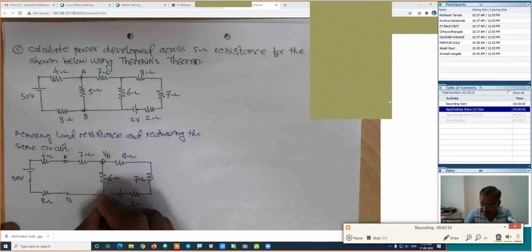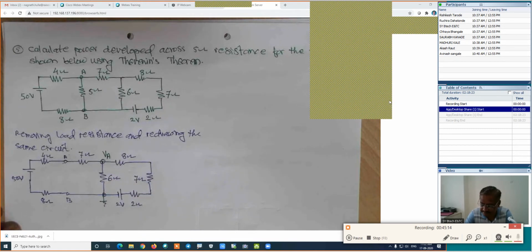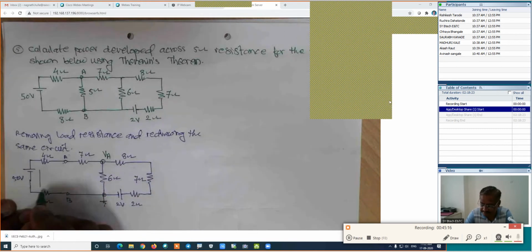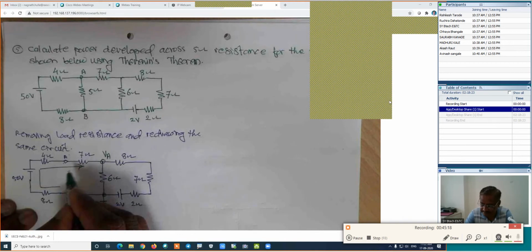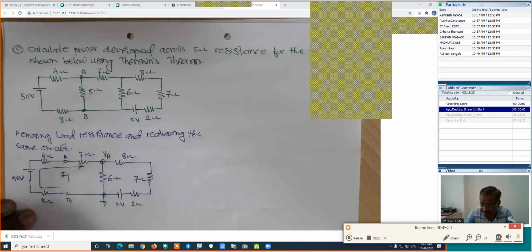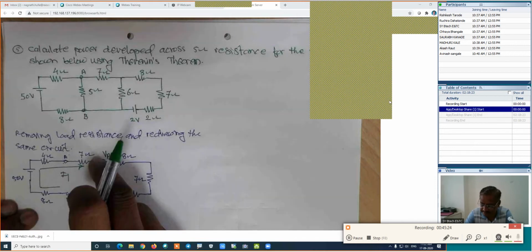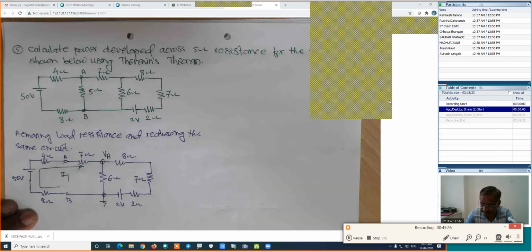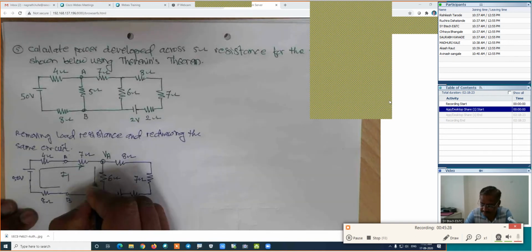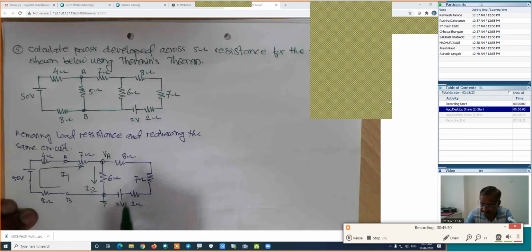This is the node A having its potential VA, and this is the ground node. This complete branch is one branch. What is the definition of a branch? A path between any 2 nodes. This is one node, this is another. This complete path is one, with current I1. This is the second branch, its current is I2, and this is the third branch, its current is I3.